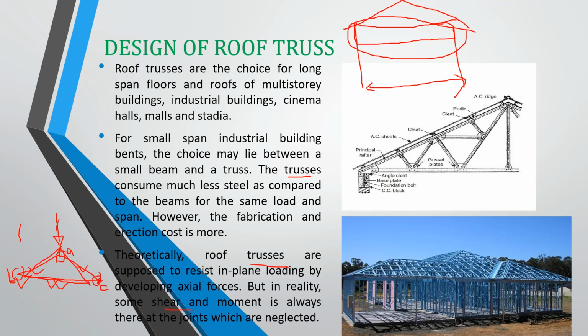Because of the use of multiple bolts or welding for connection, that introduces rigidity at the joints between the ends of the members. And these end moments, because of the rigidity, give rise to the secondary stresses. So consequently, these members are subjected to moments in addition to axial force, generating secondary stresses. And these secondary stresses can be computed.